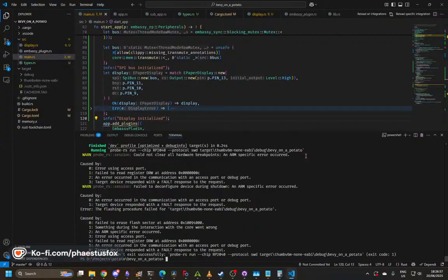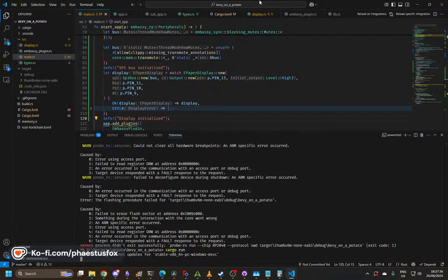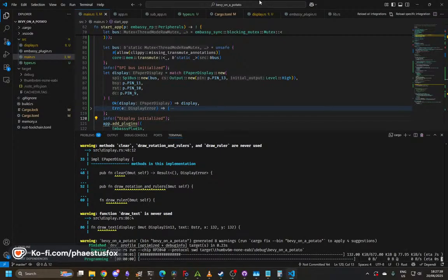So between here and, I think it's this one, is ground. Okay, 3.3. So you are getting 3.3 volts to your red wire, which is your VCC. And then the ground, wherever the ground is going. Okay, question. Between you and you, is there 3 volts? No, if I had it the right way around, there is 3.3 volts between you and you. So it's definitely getting power. Again, it didn't like whatever I did. I apparently reset it, which is not a good sign.